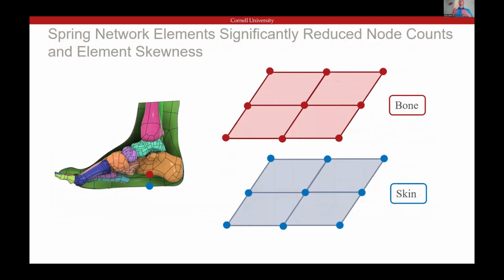All right, so with the bone and the skin modeled, we have all the rest of the volume of the foot to model, which is going to be classified as a bulk soft tissue material. With this amount of space that we have, this would require a large amount of elements and nodes, which would slow down the solver.